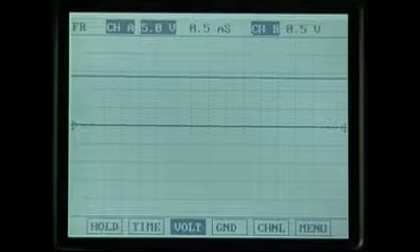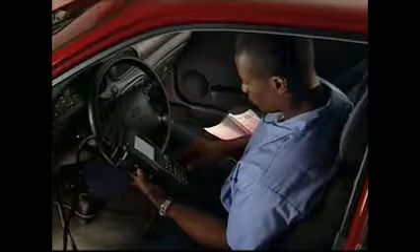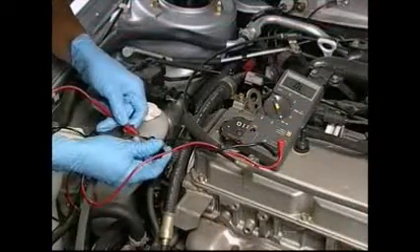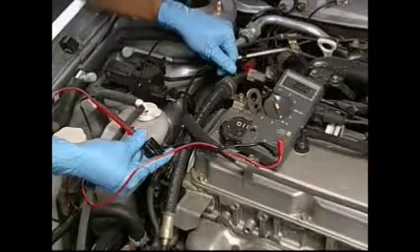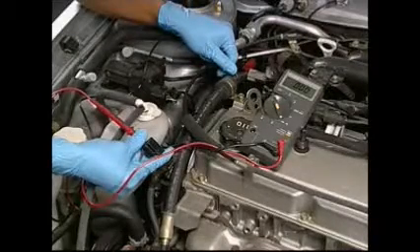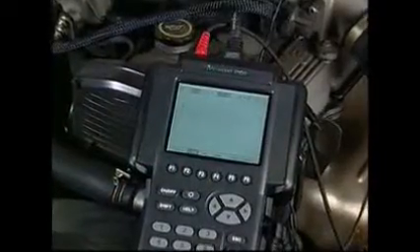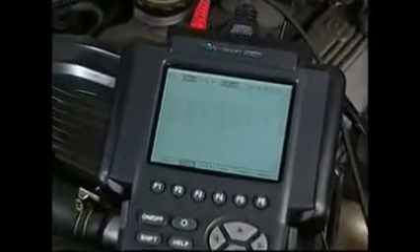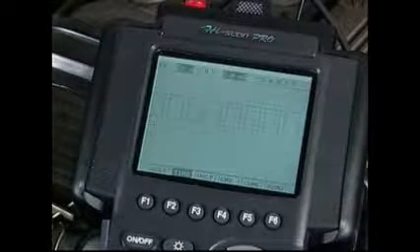For basic electrical diagnosis, you can use the oscilloscope storage feature to test for intermittent conditions. The leads on a digital oscilloscope function the same way as those of a digital multimeter, although most oscilloscopes have separate wiring harnesses for the probes that attach to one port. The benefit of an oscilloscope is that it has a memory that can track a voltage signal over time. If you suspected a poor connector, you can probe the mating terminals with the leads of the oscilloscope.